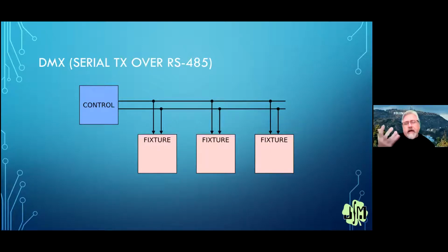You'll often hear DMX, I generally call it just DMX, but you'll see it called DMX 512. There's actually 513 bytes transmitted because the first byte, the 0 byte of the packet, is called the start byte. In DMX, that's always 0.